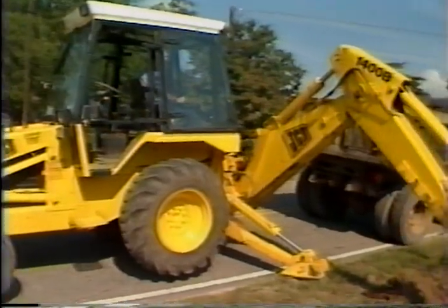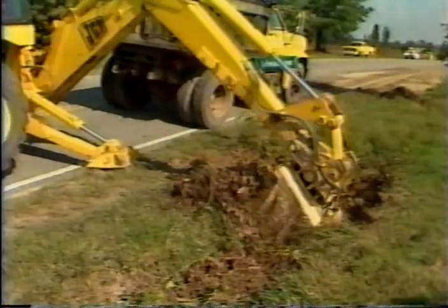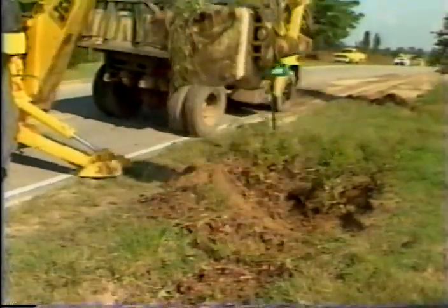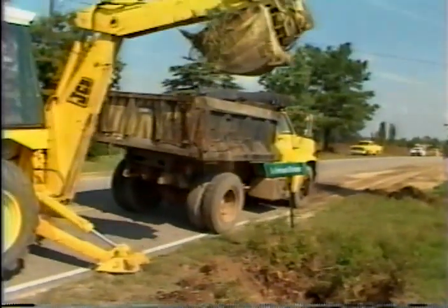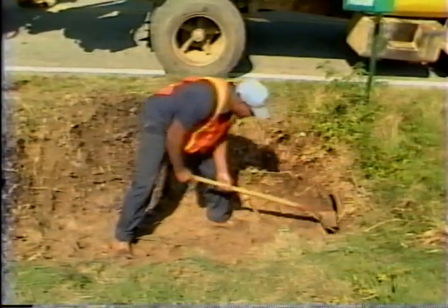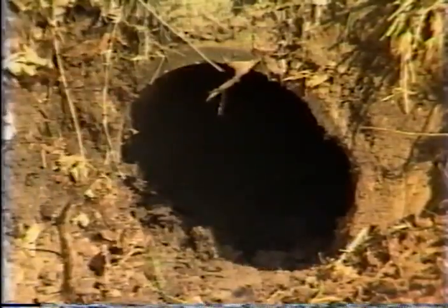Prior to using the motor grader, use a backhoe to clean out around pipes and outlet ditches. It is difficult for a motor grader to clean out properly around the ends of these pipes. If necessary, do this by hand and remove this material as a part of the ditching operation.